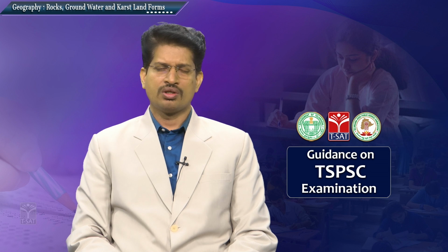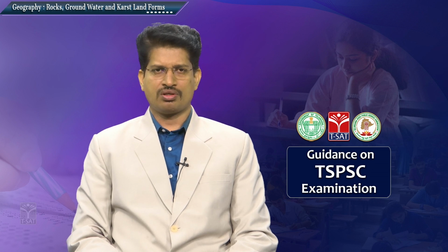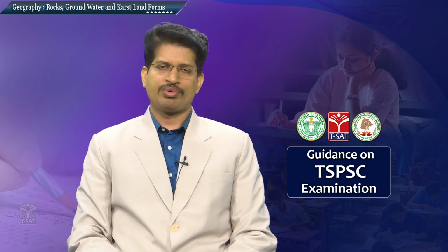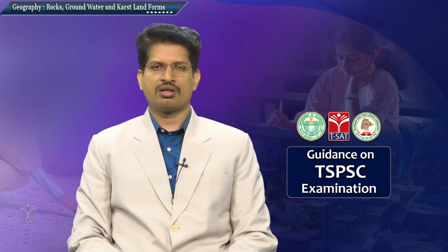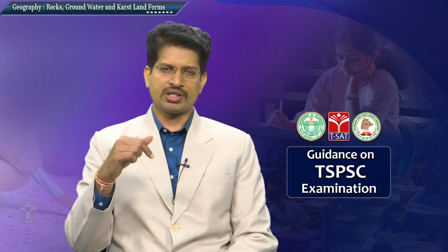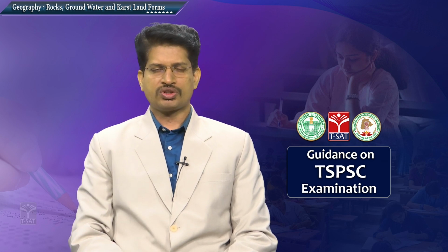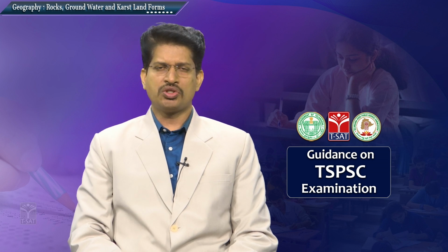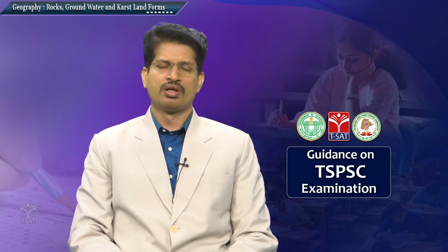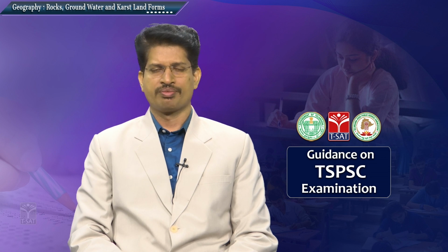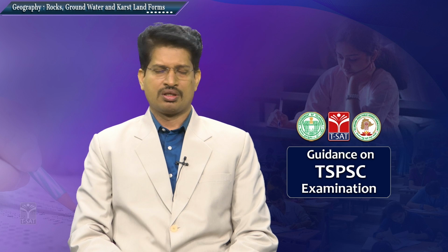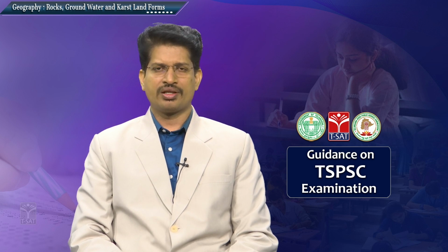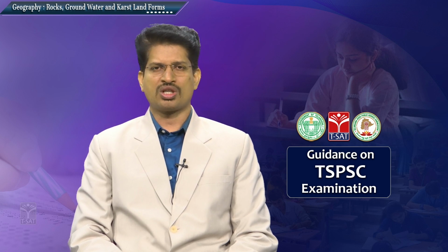When it rains, because of gravity, the water flows. The flow of water happens in two ways. One is surface runoff, the second is percolation of water vertically downwards. Depending upon the nature of the rock in terms of porosity and pervious nature, the water percolates down. In the absence of porosity, the water doesn't percolate down. The water is subjected to surface runoff.